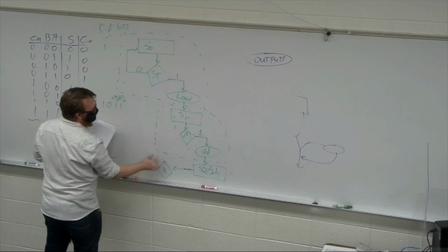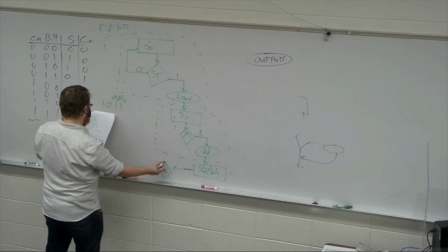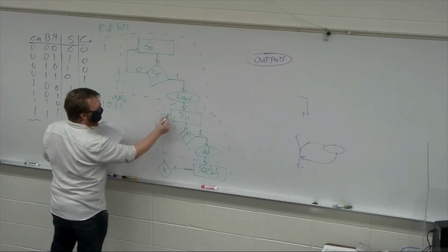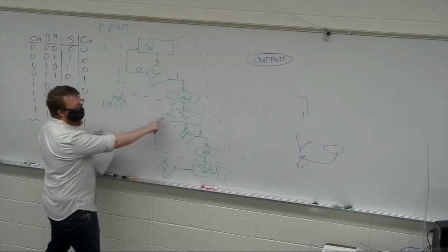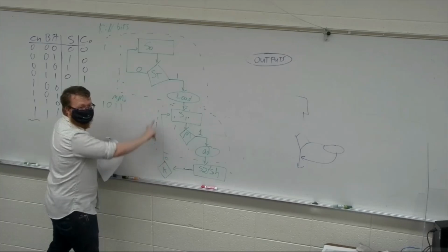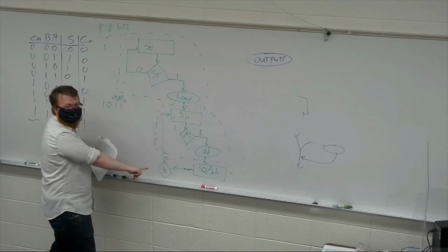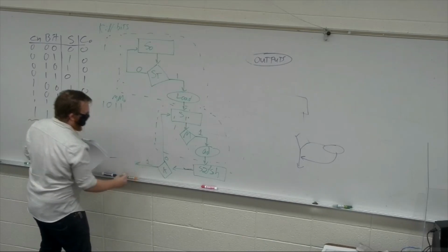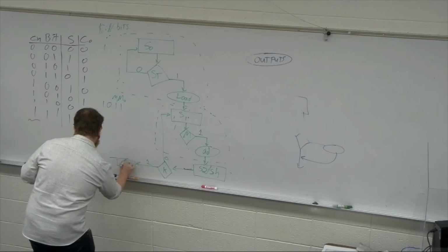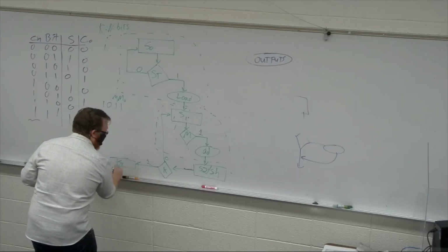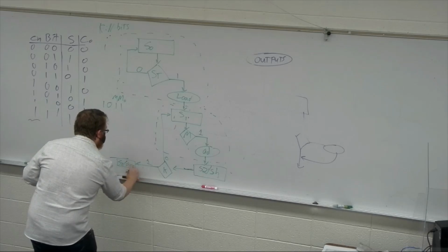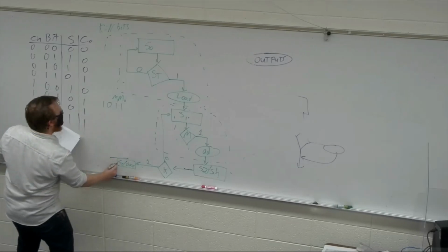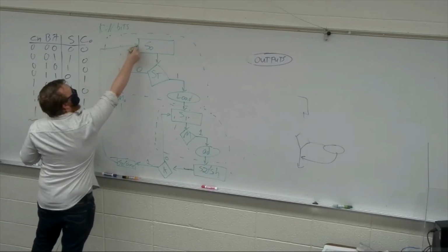And we're going to go ahead and feed this back into, where do we need to go? Back into S1. Right, because I need to start deciding add and shift for as long as I need to until I've reached K, until I've added and shifted all the times that I need to. If I have reached K, I'm going to go to a new state S3 and assert an output called done. We're done with this, and then we're going to feed all the way back to state 0.